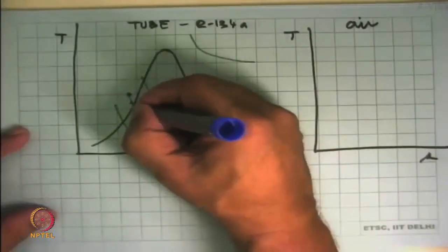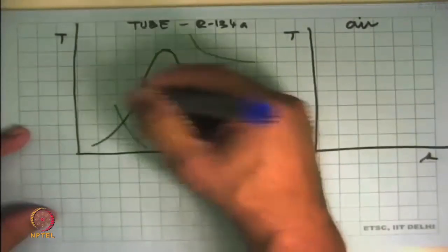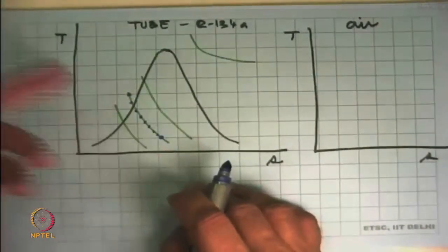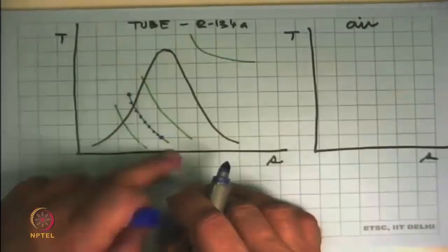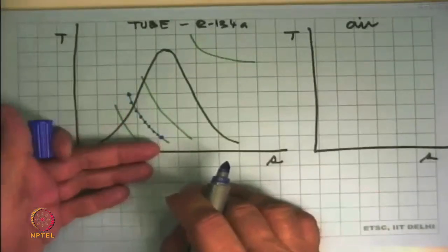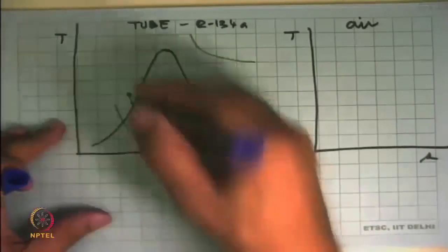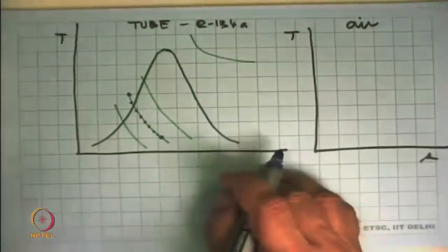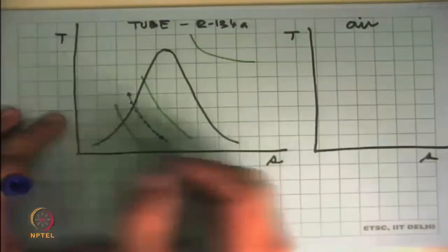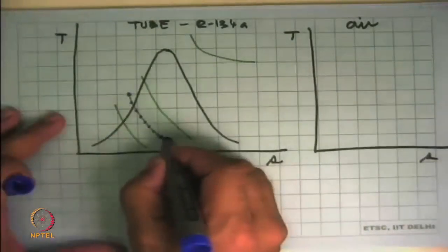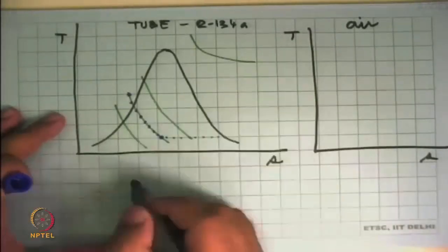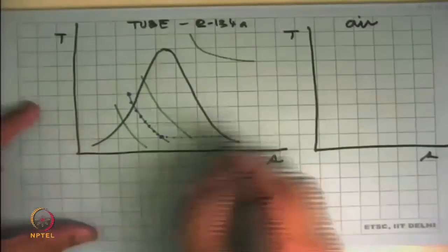The one way to show it is that we put dotted or dashed lines along this line and say, look, it is irreversible. That's number one. That's why I'm not drawing a solid line. And second, I'm superposing it on the constant enthalpy line just to tell you that this is a constant enthalpy process. But otherwise, any other line is fine because it is irreversible and the intermediate states are not actually known. So this is the inlet state to the evaporator. From there, it goes off there. And then what has happened here is that this phase change is at constant pressure.